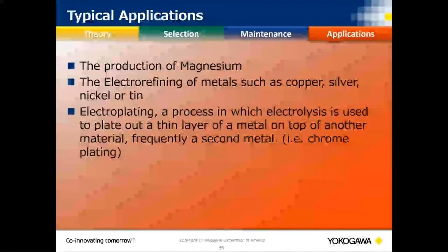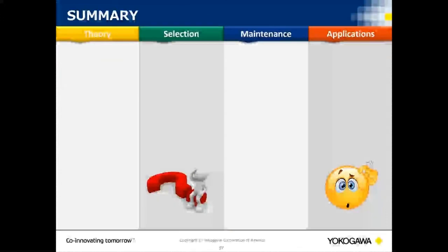And then even in the electroplating applications, besides the chromium and the cyanide reduction within the process itself, they have ORP measurements that they have to maintain in the baths, and they have to maintain certain ORP values for a certain amount of time. So those are the most common that I have seen or found.